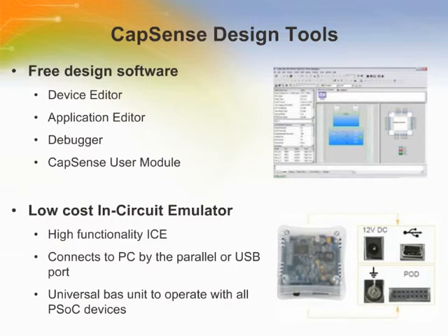Cypress has a suite of design tools, starting with the free integrated development environment, PSoC Designer. PSoC Designer allows engineers to define the system parameters and select, place, and configure predefined analog and digital functions using the device editor. CapSense functions are included in the library of functions. The screenshot on the right of this screen shows the device editor for PSoC Designer, allowing engineers to write application code with the application editor and step through the program with the debugger.